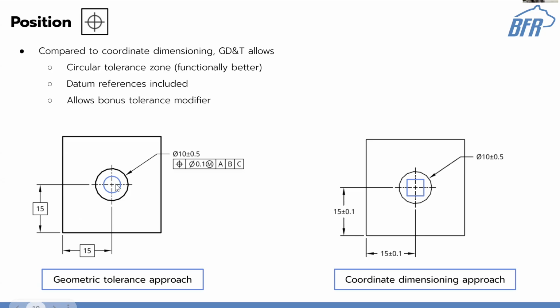And let's say I'm trying to fit this up against another plate that has a bunch of holes in it, right? I need to make sure that these holes overlap. But with different diameters, maybe there's a little bit of wiggle room before my secondary hole that I'm trying to control is no longer fully overlapping with the other one, right? And that would be failing its functional requirement. My bolt no longer passes through the hole.